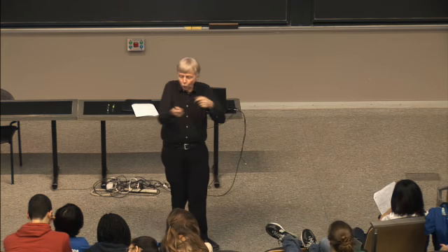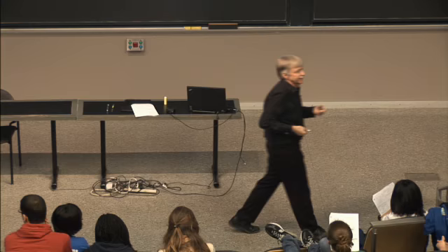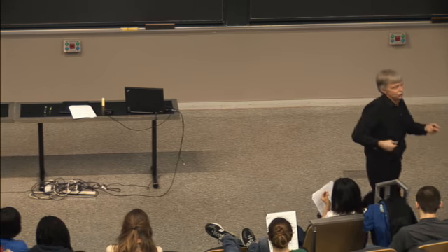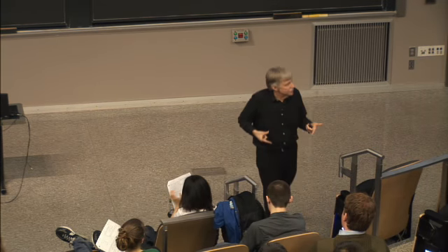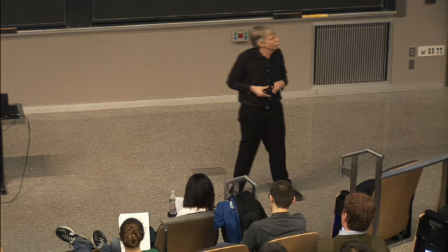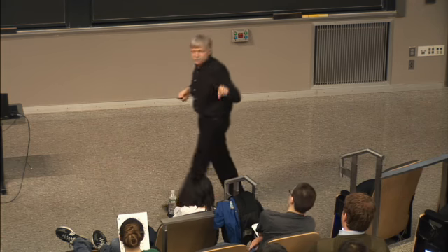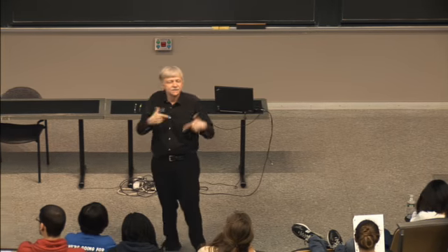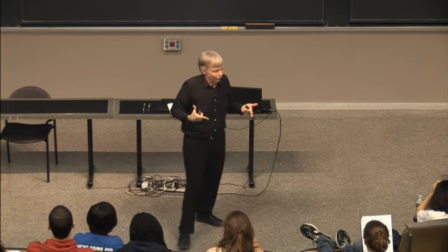So it has a practical value because it's the way you specify an electronic part. When the manufacturer makes a part, they can't know what you're going to do with it. So they tell you how it works by telling you something about the equivalent circuit. There's also a different reason for thinking about this, and that is because it's conceptually simplifying to think about Thevenin